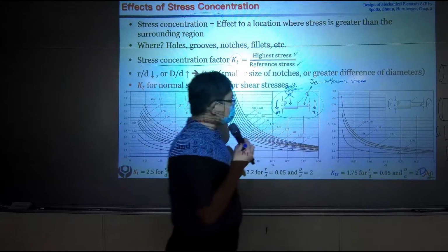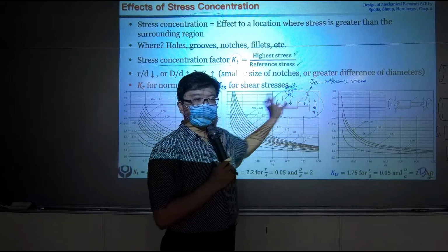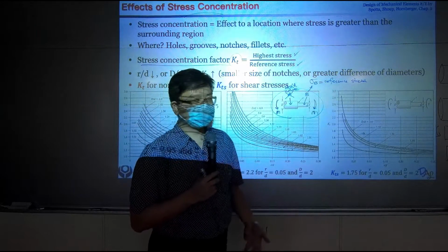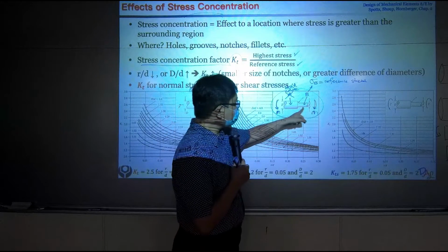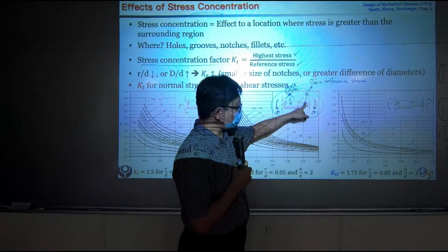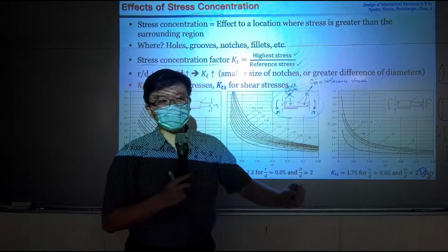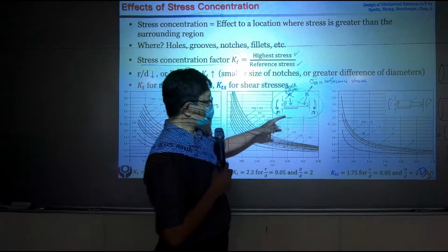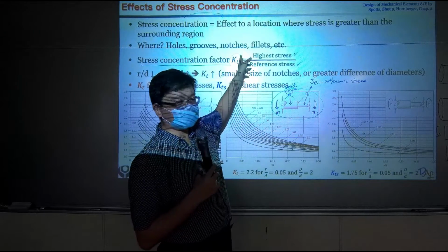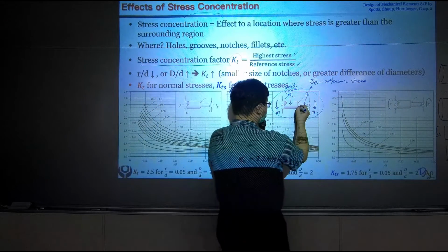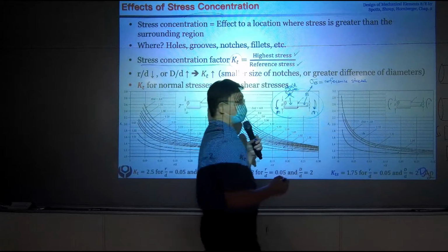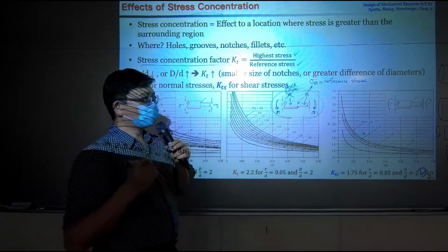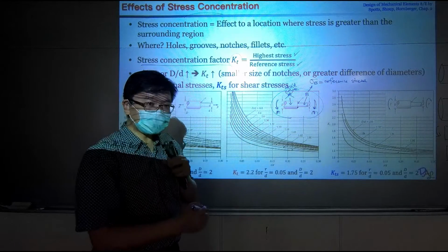So in this case, this is where this workpiece is carrying the most stress. But besides the stresses inside region B, there are some positions that could be having even greater stresses due to the effect of stress concentration. These are those corners.